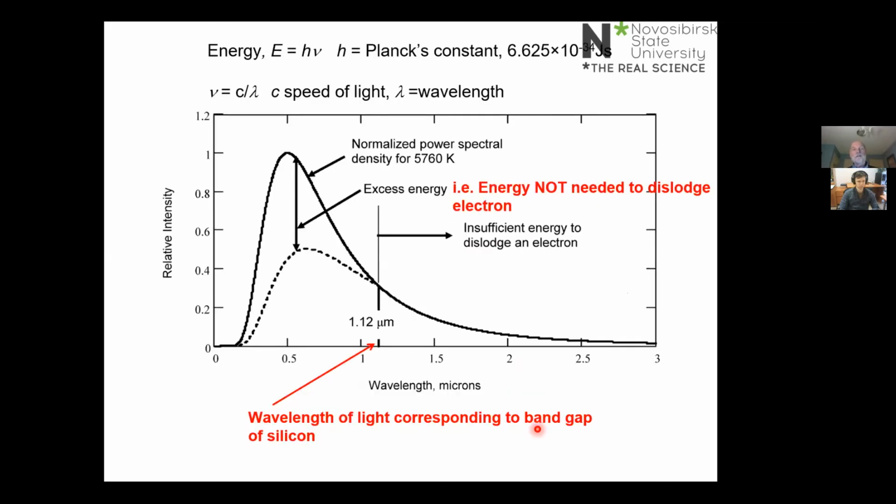And the significance of it is that if we look at the spectrum of the radiation versus wavelength, then the fact that there is a finite amount of energy required to move the electrons into the conduction band means that there's a range of wavelengths that a particular PV technology cannot use. So the band gap for silicon actually corresponds to a wavelength of 1.12 micrometers.